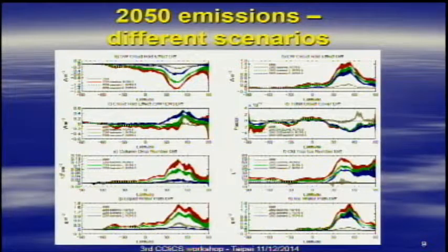So here are just the aviation so-called all emissions: water vapor, including also aviation aerosols. The black is the 2006 level, the red being the baseline in 2050, the green being the 2050 scenario 1, assuming a 2% increase in engine efficiency. The blue being scenario 2, same as scenario 1, but you lose all sulfate emissions.